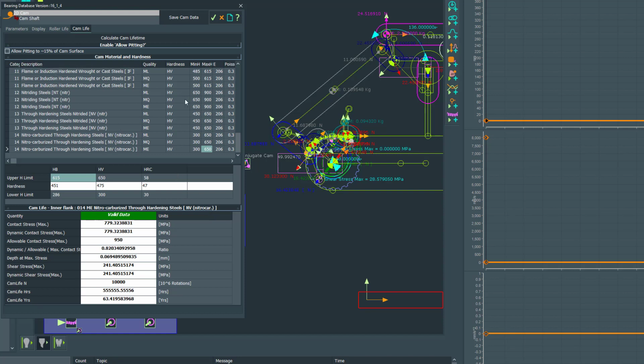At the top here is where we can select the material. Now the way that the ISO standard works for gears is that rather than having a large selection of steels, they categorize the steels, and this is because they've, I guess, experimentally verified four separate fatigue curves, or SN curves. So each of these material categories here will obey a certain fatigue curve.